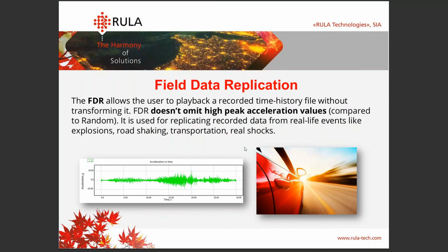Comparing field data replication to basic test types, there is a notable distinction. While sine test type applies a generated periodic waveform and random test type utilizes a spectrum of varying frequency signals to simulate unpredictable environments, field data replication directly reproduces the recorded responses from the field.